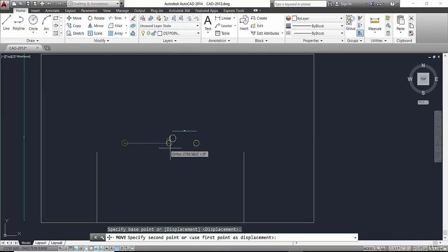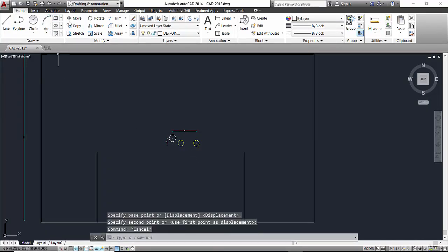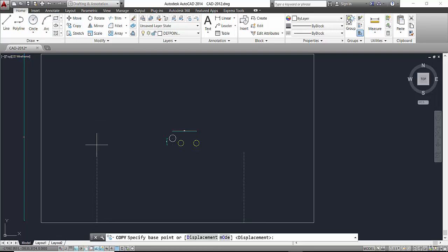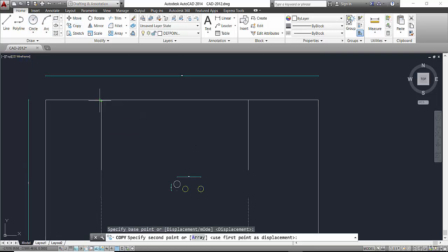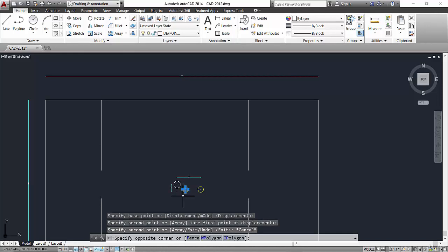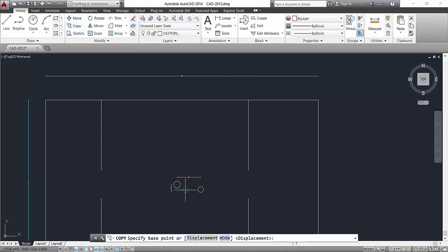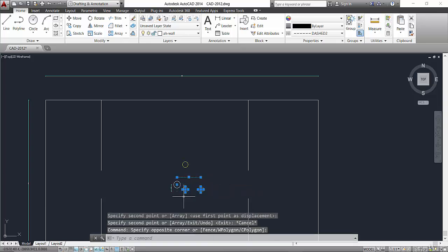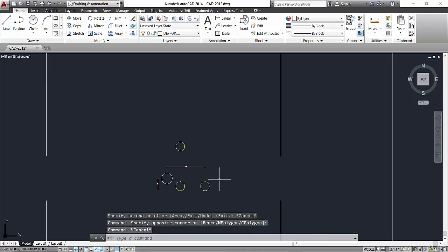And if we have shear walls here, the center of rigidity will move up to here. So the center of rigidity is related to the position of the shear walls. The more the shear walls are symmetrical in the plan, the closer the center of rigidity is to the center of mass.